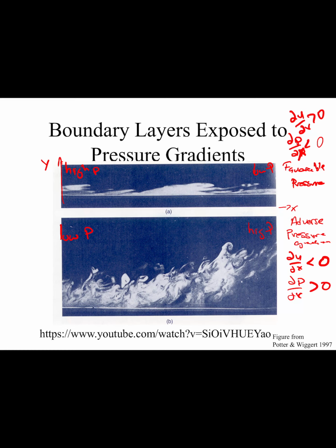And so you can see that as the flow accelerates, the boundary layer becomes thinner, and as the flow decelerates, and it's already zero at the wall where we have our no-slip condition, you can see that this becomes very, very thick, and actually at some point separates from the wall, and that's a key feature that we're going to discuss.